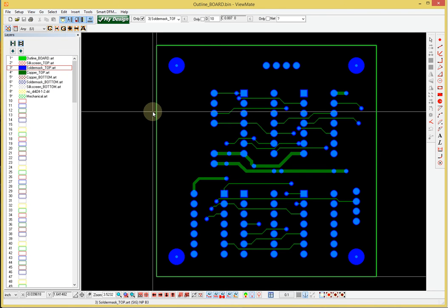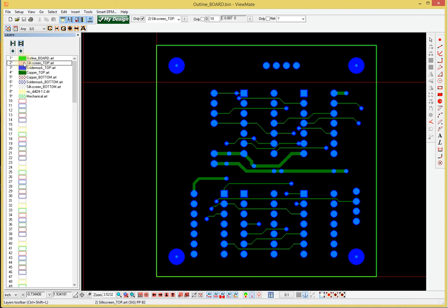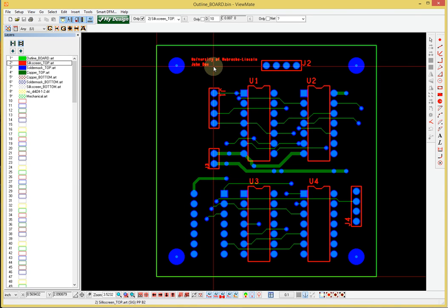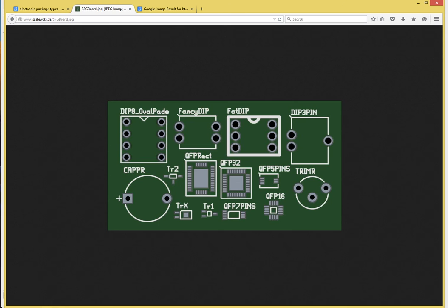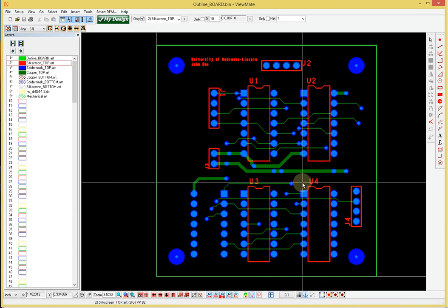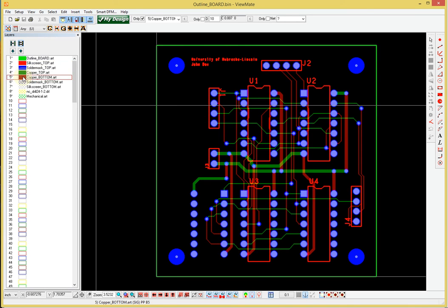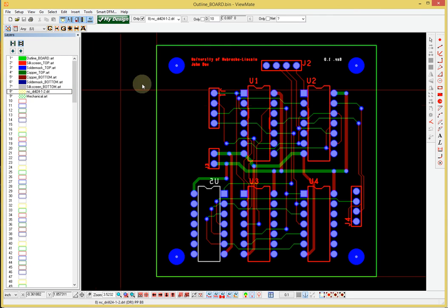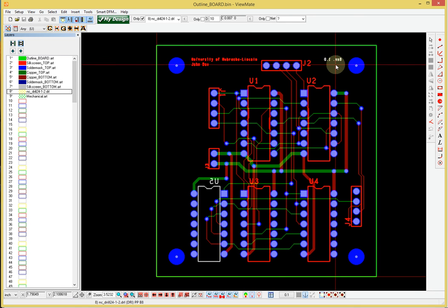And then after the solder mask, we have the silk screen, which basically is a legend. It's usually in white, and I show you that over here in this image. Basically, all of this is just painting that is applied last on top of your solder mask, which is usually green. It just gives you information of where the parts are, what the reference designators are, etc. And then the same thing for the bottom layers. And then we have the complete board.